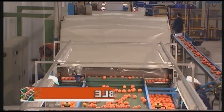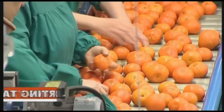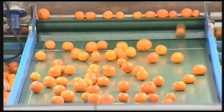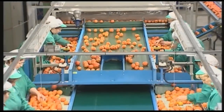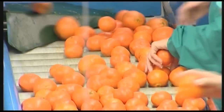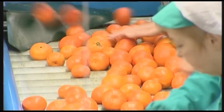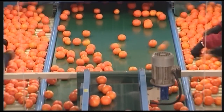The spinning rollers of the sorting table rotate the fruit, so that the operators standing on platforms located along the sides of the machine may view it in its entirety and separate it manually according to quality. The inferior quality fruit is deposited directly onto a conveyor belt or through a chute if the conveyor is installed below the machine. The fruit is sent to different sections of the installation once it has been sorted.